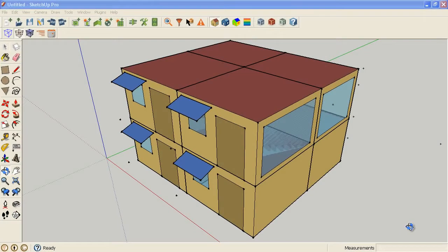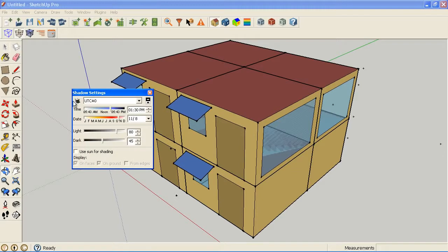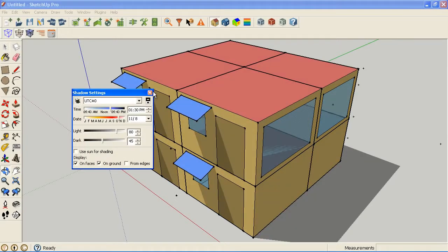Okay, so here is our 8th zone model, and right now I'm going to turn on the sun just to make it more obvious, but we don't really need to. So right now, if there was no mechanical system in these zones, and let's say it's summertime, these zones are going to get hotter and hotter, as the individual surfaces as well as the temperature inside the zone, because there's external loads acting on the building.